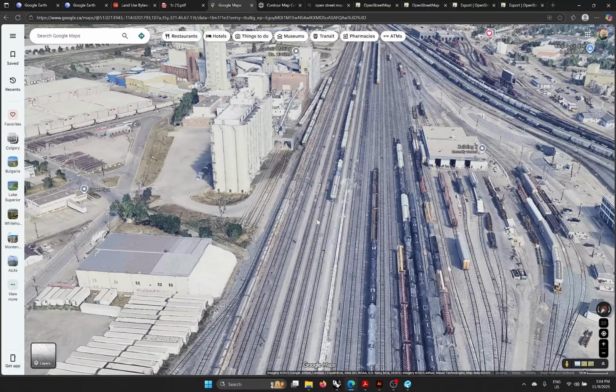So once we're in Rhino, you just want to make sure that you do a file new. I'm just going to save this. And then we're going to do large objects and in meters. So large objects, we're dealing with very big sites at the 1:1000 scale, and we're dealing with meters because most site plans are going to be dealing with this unit. It's large areas again. So make sure that you have those two set up.